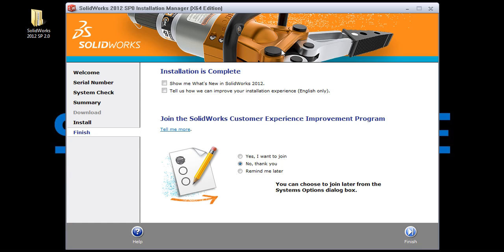And I've seen quite a few times where the installation failed on the first attempt but went through perfectly fine on the second attempt. So the first thing you'll do is try to install SolidWorks again after restarting. Also, like I had said earlier, if you're installing from a DVD and it fails, you'll typically want to drag the files onto your hard drive and see if that fixes the problem. If the installation fails multiple times, then the issues are generally more complex. Sometimes you have to reinstall a component that SolidWorks needs within Windows to be able to install. And sometimes you have to uninstall various programs or move a few things around in order to get it to work.